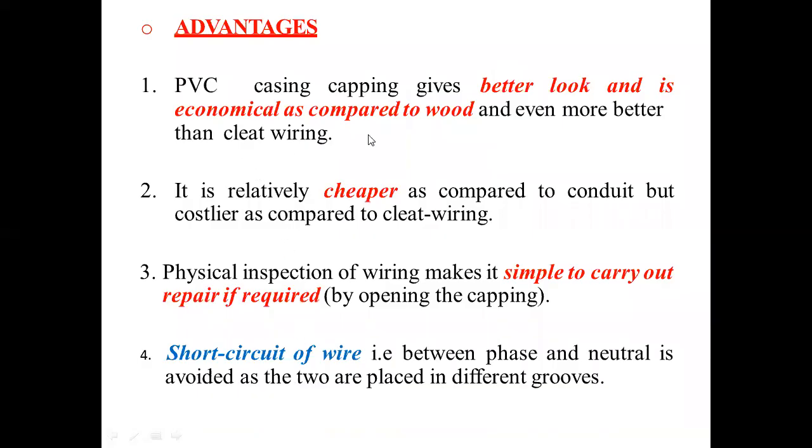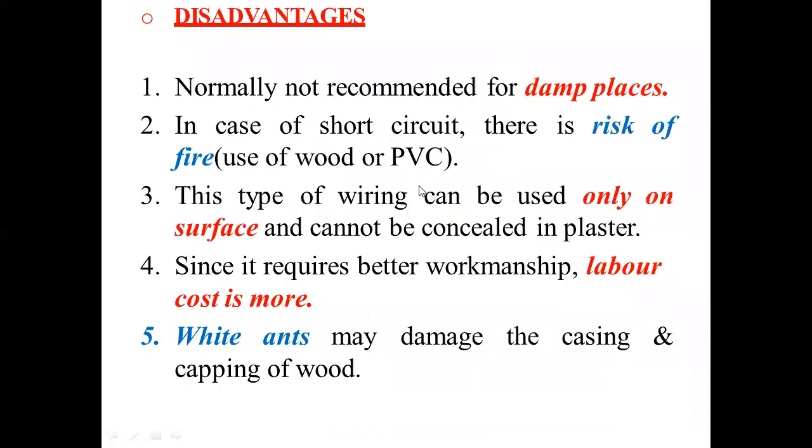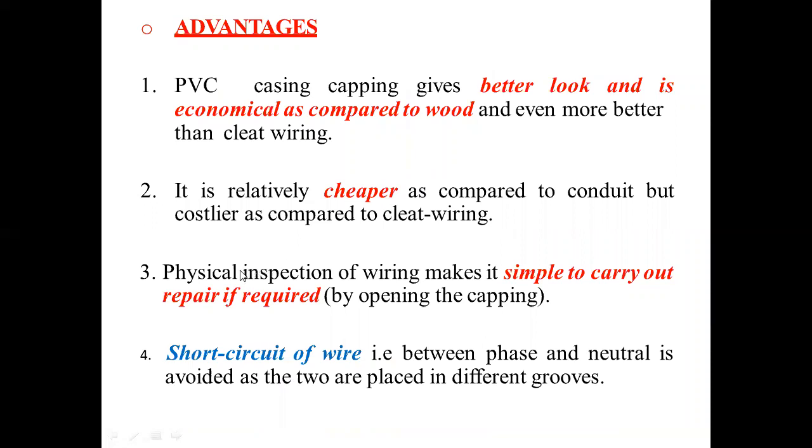And the advantage is better look compared to the cleat wiring, and economical compared to the wood. And it is relatively cheaper as compared to the conduit. So if you compare the conduit, the next type of wiring, its cost is less, but costlier than compared to cleat wiring. But from the safety point of view, it is very high compared to the cleat.